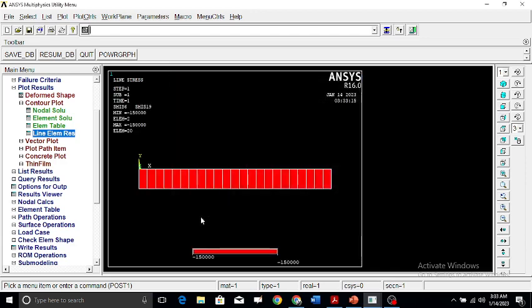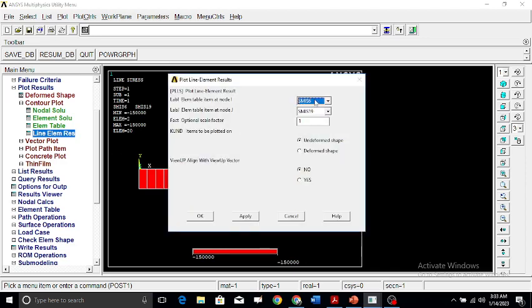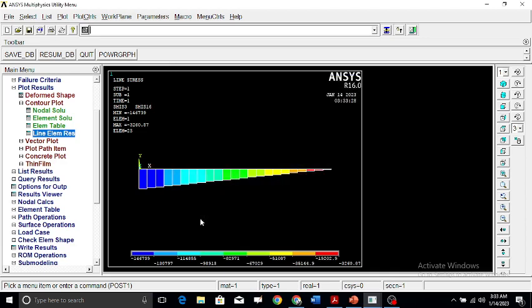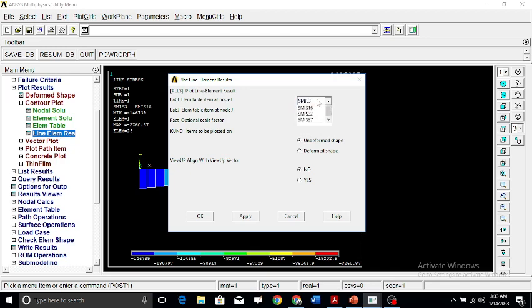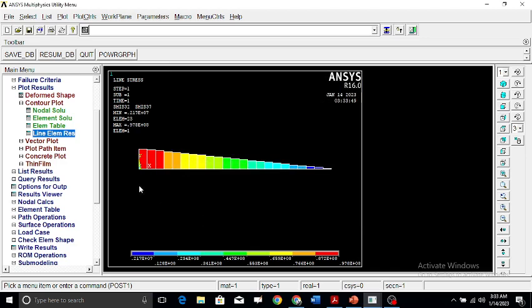All right, this is our shear force diagram. If you want to see your respective bending moment diagram, remember it was 3 and 16. Let's start with that. So this is your bending moment diagram being generated. And if you want your bending stresses, it will be 32 at node I and 37 at node J. You can see these are the bending stresses being generated of the structure.